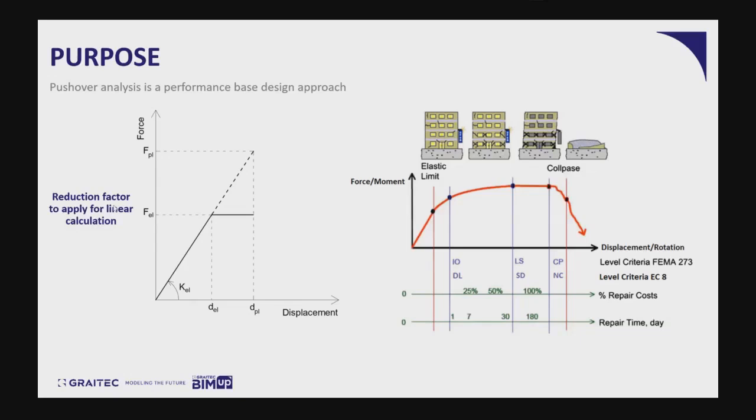Now, with the pushover, it is a performance-based design. In pushover, we go into the nonlinear domain. We do nonlinear calculation. We know that our internal forces are capped at a certain limit, which is the elastic limit. Now, what interests us in the design is how far the structure exhibits plastic deformation. So this becomes the design criteria. The performance of the structure is now the base of the design. From here comes the name performance-based design.